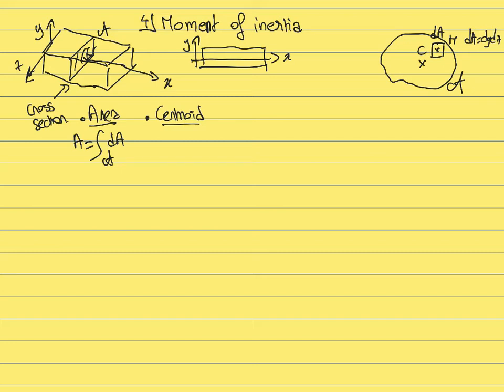The average value of x over the entire surface and the average value of y over the entire surface will give you the geometrical center of this surface, which gives you the coordinates of the centroid C. In this case, since the surface is defined along the y and z axes, the surface is orthogonal to the x-axis. The x-axis is pointing towards you. It's orthogonal to this cross-section.